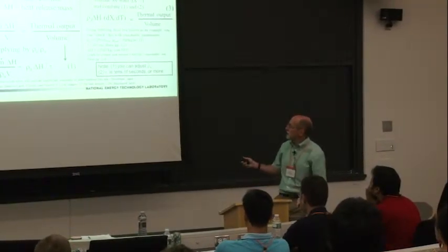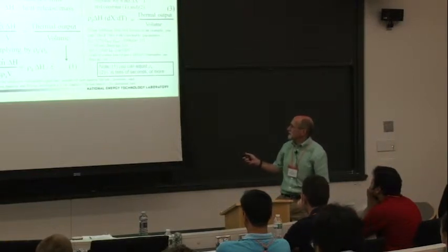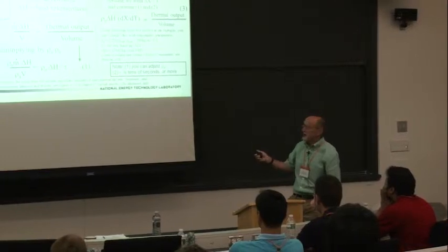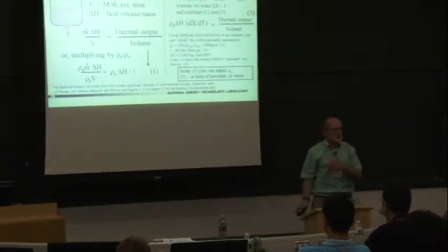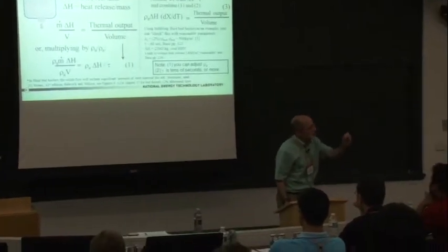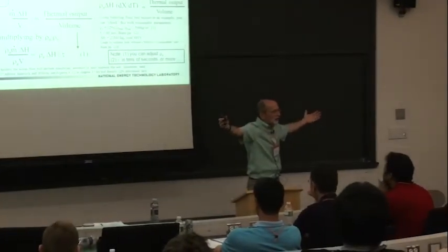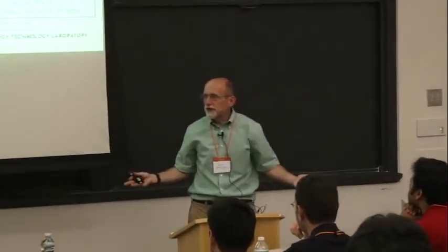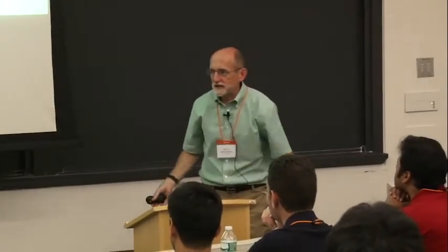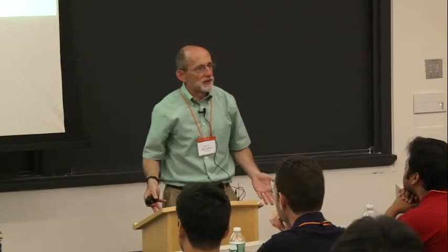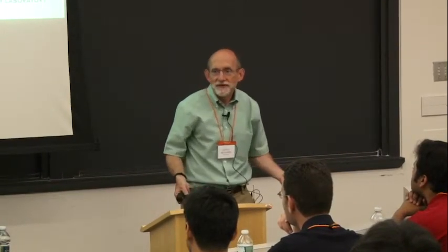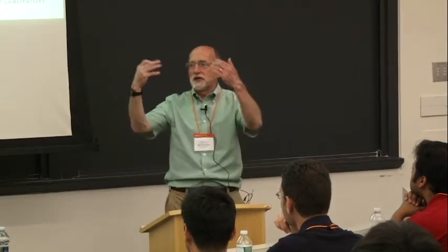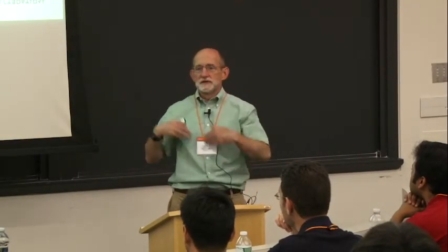Second thing, and this is the part that's hard to appreciate until you work on this for a little bit: you can actually adjust the active density that's in the bed, right? Again, I said it's not the density of the particle, it's how much is in that bed volume. So you could imagine diluting the bed out, right? Put sand in it. That's what you do in a fluid bed. Fluid bed combustors today, only about 2% of the bed is the coal. The rest is just sand going around in there to keep the temperature nice and even, all right?